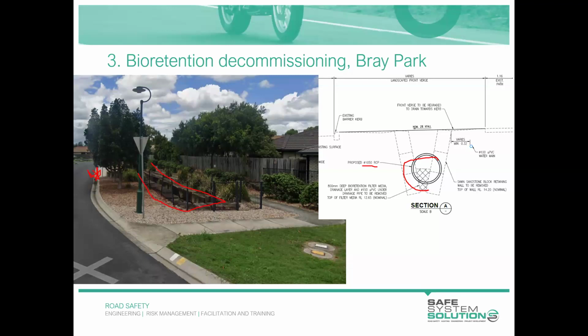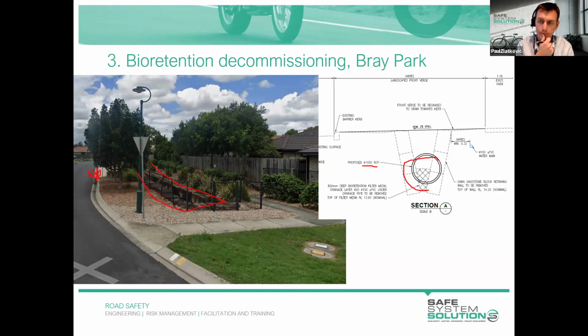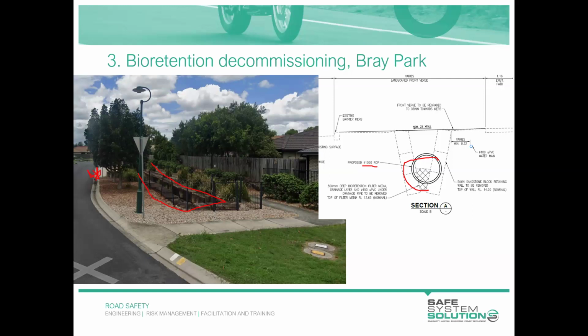Some of the risks we identified were mostly around construction: working near the roadway, deep excavations, trench collapse, falling, heavy lifting with machinery to remove the sandstone blocks and install the large pipes. There's risk of rupturing the adjacent water main when the blocks are removed and the ground's unsupported, and confined space access from a maintenance perspective.